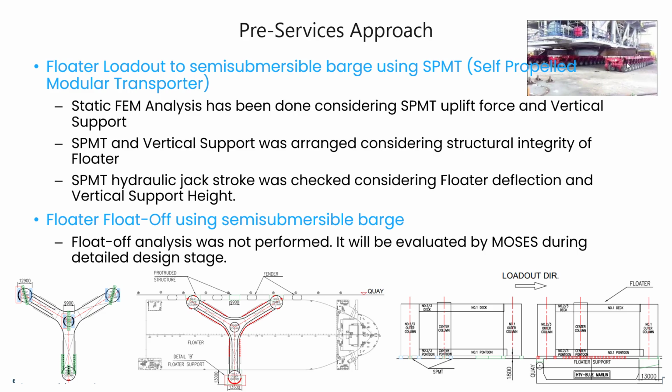For reference, MOSES has long been used for similar analysis, such as caisson installation from a floating dock or buoy separation from a barge. MOSES handles these analyses as a series of static analyses with varying ballast conditions and can optimize the ballast configuration for each step of the lowering sequence.